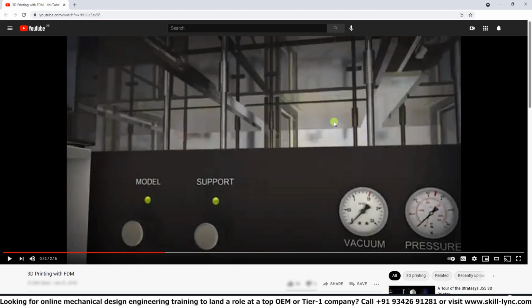So that's why in more expensive FDM technologies used for industrial applications, used in different companies to create their prototypes, they try to not sterilize but control the workspace and build environment more accurately in terms of humidity, moisture, air temperature, even pressure and whatnot. So it gives you a better idea of some of the elements that can have an effect on your models produced.